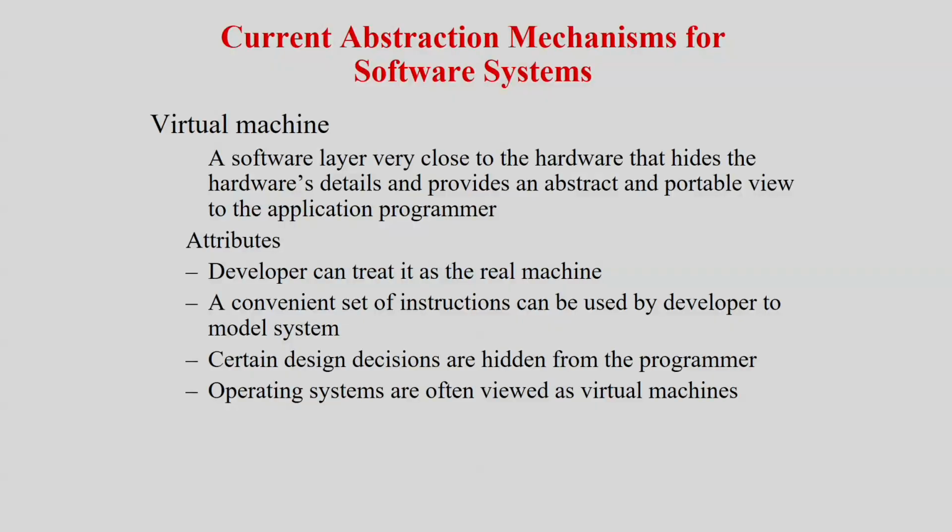And also I can delay the partitioning. I can have an initial big model, and then go through quick iteration. When I have a more or less complete system idea in my mind, then I can decide, okay, this I put in hardware, this I put in software. So this will give you better debugging capability, better test capability, better solution efficiency and so forth. But the only issue is making such an environment. People call it a virtual machine.